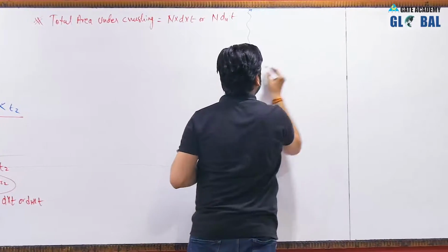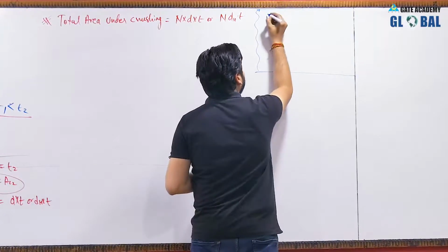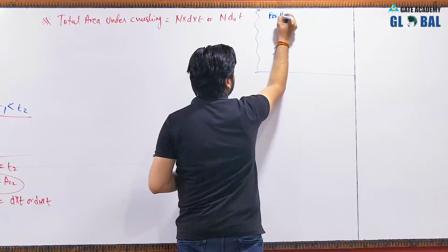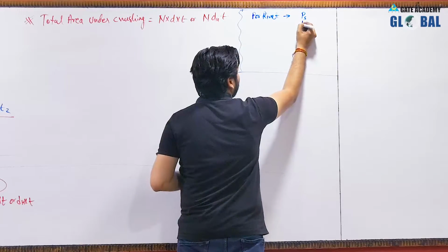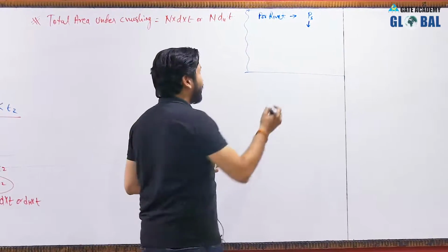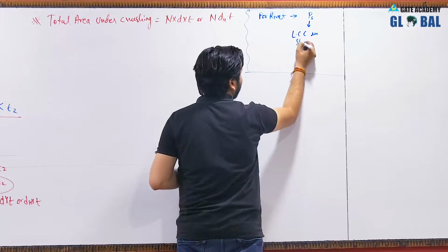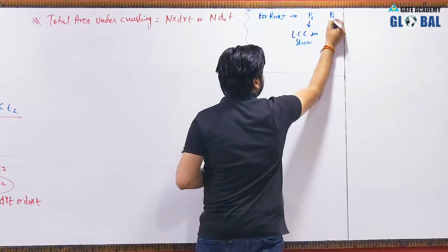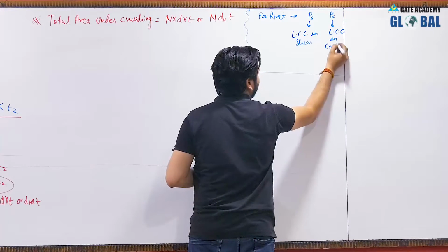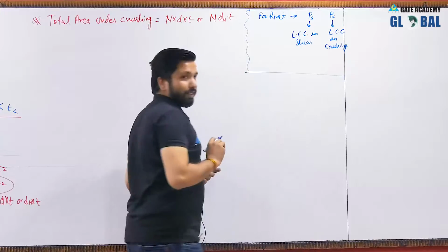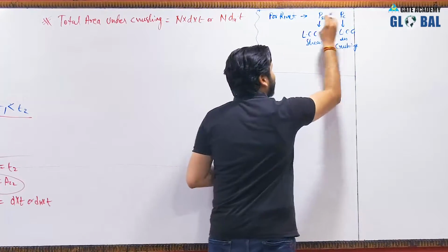Again, if you want to note it down with this numerical only, then you can also make a separate note along with the numerical, that for rivet you will be having PS, that is the load carrying capacity in shear, and PC, that is load carrying capacity in crushing, okay, and the strength of rivet will be the lowest among these two.